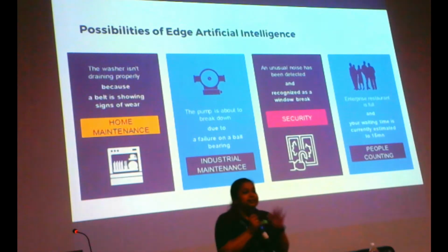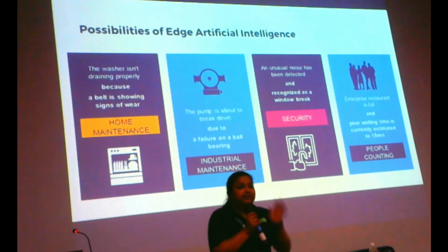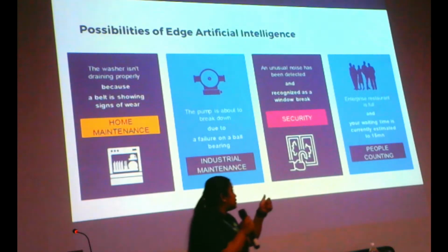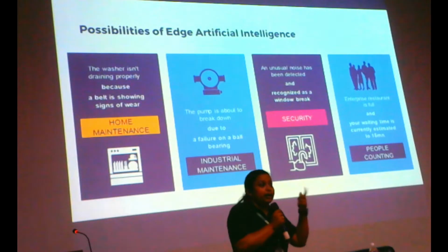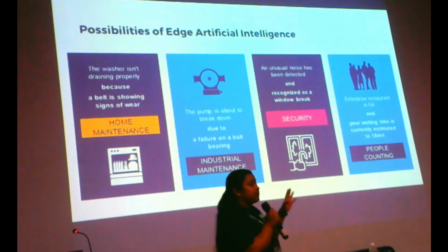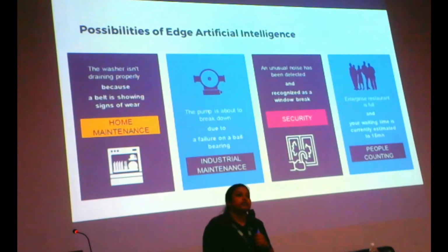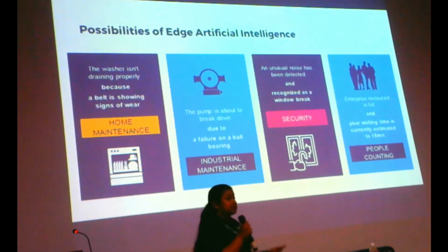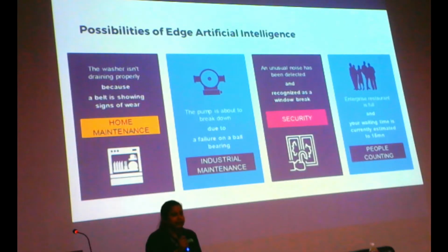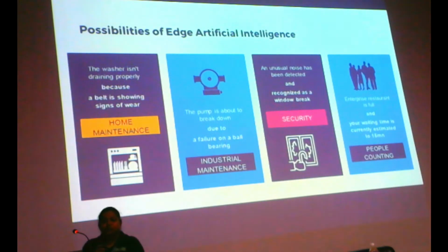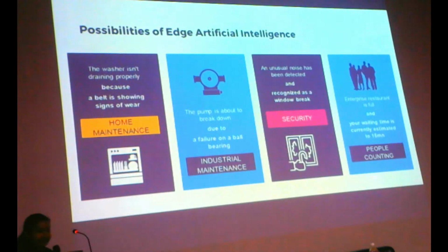So this is not camera based. This is sensor based only. Based on a TOF sensor, you can use it. This people counting system is without the camera. With a camera, you can go for a vision AI application. This is just an AI application, like a TinyML application, which is very basic microcontroller mode.